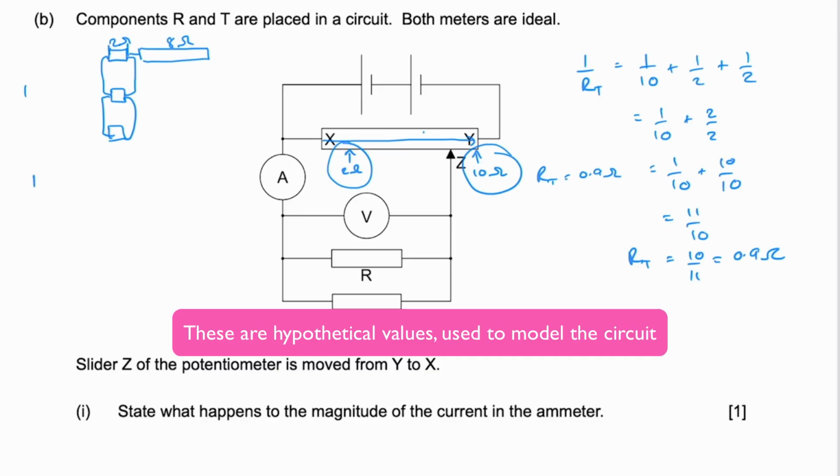So to find the total resistance, we do 1 over RT equals 1 over 2 plus 1 over 2 plus 1 over 2, which gives us 3 over 2. So the total resistance of the parallel component is 3 over 2, which is 1.5 ohms, but also it's in series with this extra 8 ohms. So the total resistance of the whole circuit is 9.5 ohms.